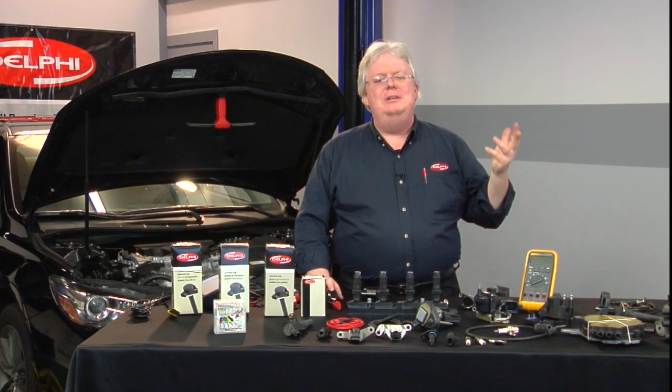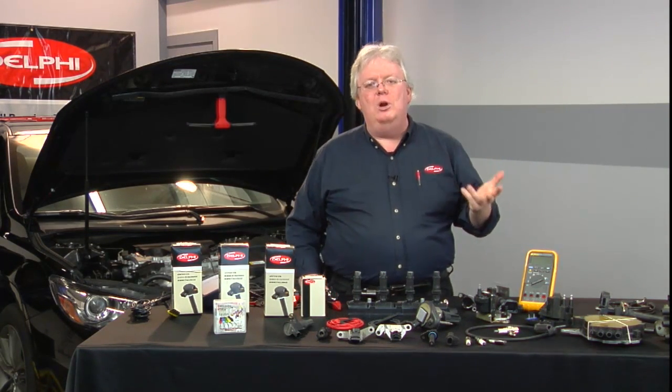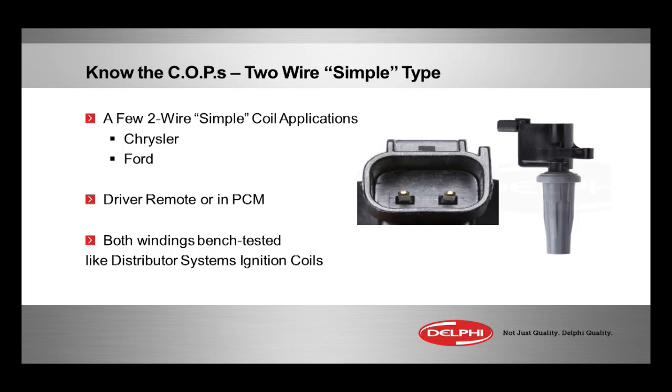A lot of Chrysler, Dodge, Jeep. We're looking at some of the Fords over the years. In fact, until most recent years, they've all been 2-wire. Just noticed this year, 2016 model year, we've seen some 3-wire smart ignition Coil-On-Plug Ford applications. But there's a remote driver.